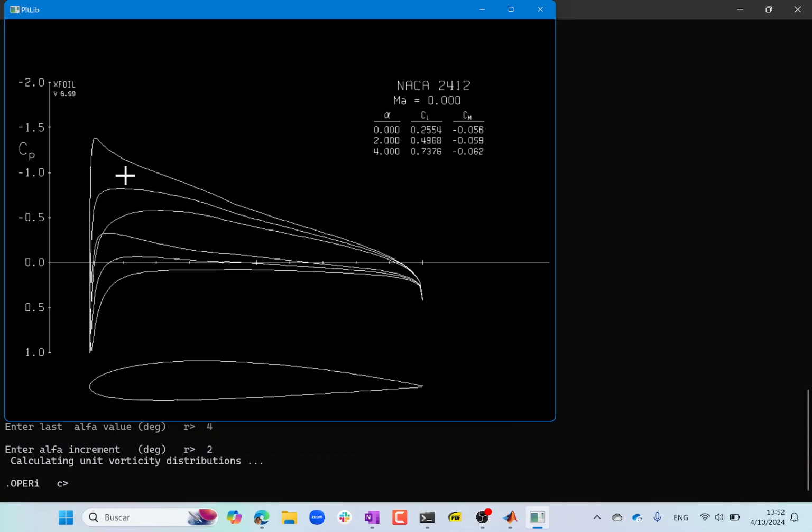You see? So somebody found the interesting thing is that the center of lift can be outside of the airfoil, right? How? If you see the pressure curve flips over somewhere in the middle, that's actually how. If you think about it backwards, the leading edge portion is creating lift, but the trailing edge portion is actually creating downforce.